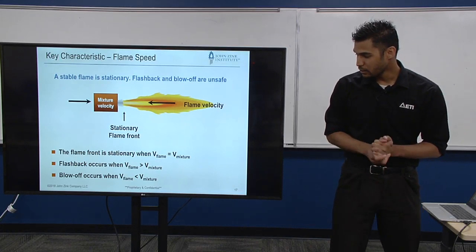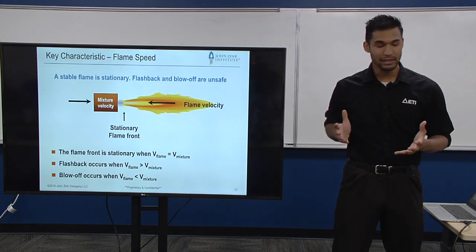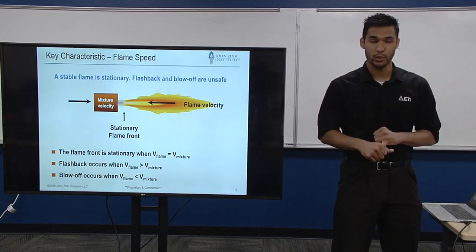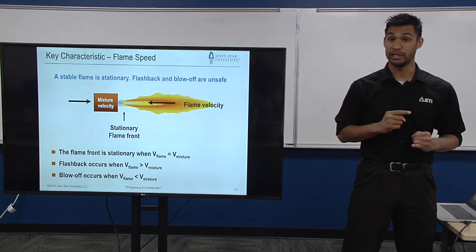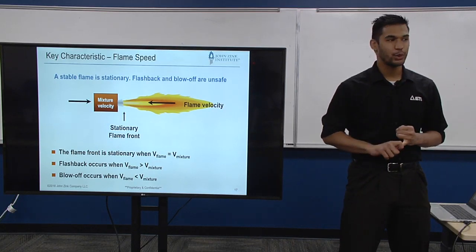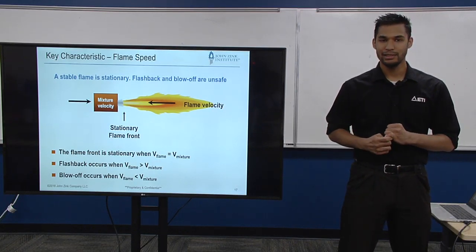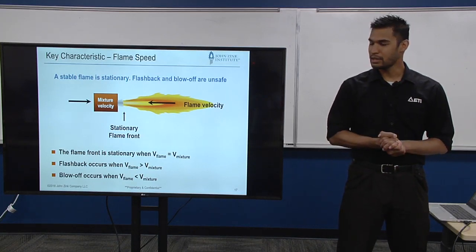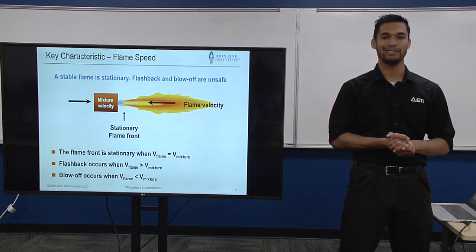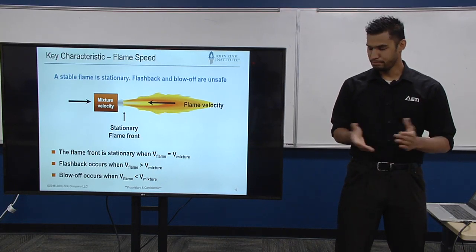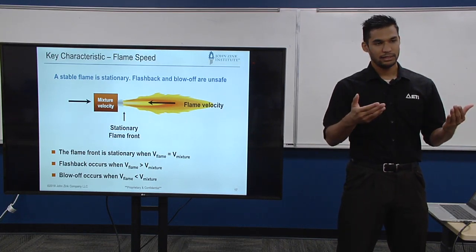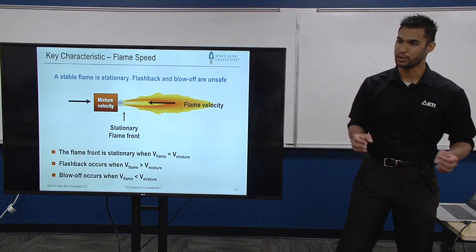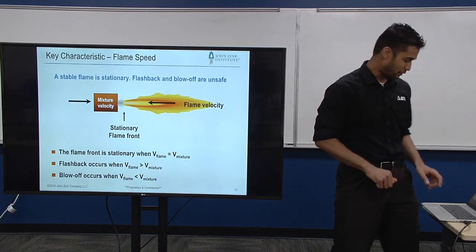And what do we have to look at? Well, a big thing that affects that is the fuel you're burning, right? If I'm burning hydrogen, well, flame speed is fast, really fast. If my fuel-air ratio is off, that affects your flame speed. Your fuel-air ratio will affect how you need to make sure your combustion equipment is designed. So, key point is, you've got to understand what you're burning. You've got to understand how it interacts with the air and the fuel. Otherwise, you will do something not safe.